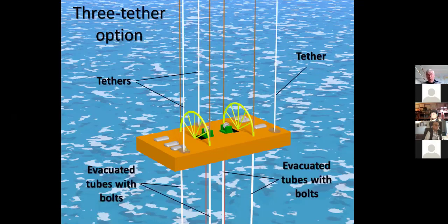And I wanted to say there is the option of having 3 tethers instead of 1, which has some advantages, and that they could go all the way up to the second stage, or they could join the main tether higher up. This has some advantages when you think about space debris, because there's just the faintest possibility that even with 2 tethers, if you're really unlucky, a piece of debris could go straight through both of them. But it's not possible for a single piece of debris to go through all 3. And that's the thinking behind 3 tethers. It's an option which will work with this setup. If you want to make them further apart, you just need to add some extra struts on the side. You could even have 4 tethers. So I wanted to mention that option.